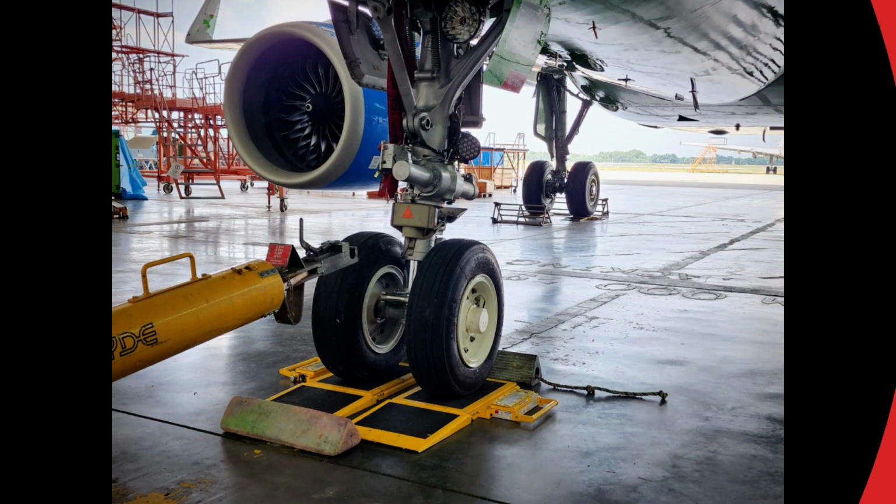An aircraft should be reweighed, and a new weight and balance record should be started after the aircraft has undergone extensive repair or major alteration, when the pilot reports unsatisfactory flight characteristics, e.g., nose or tail heaviness, and when recorded weight and balance data are suspected to be in error. Repairs and alterations are major sources of weight change.